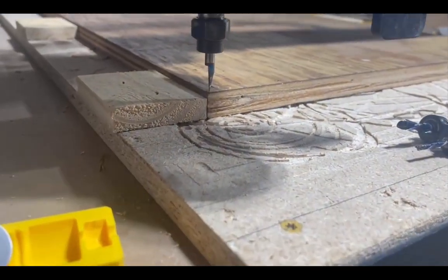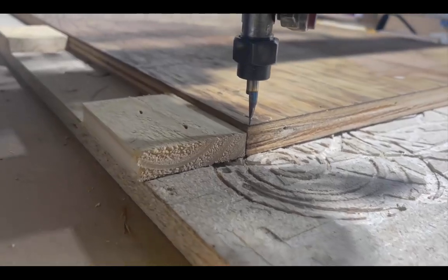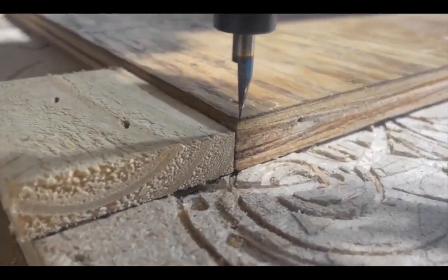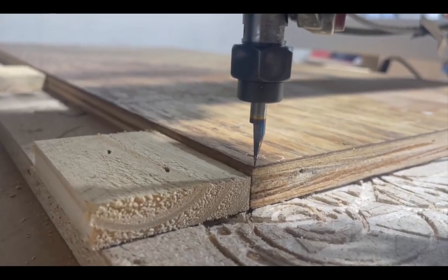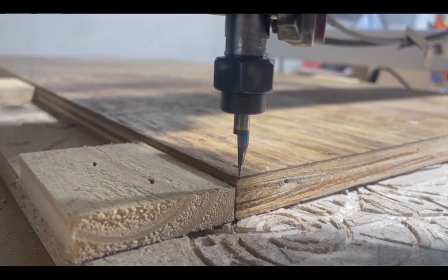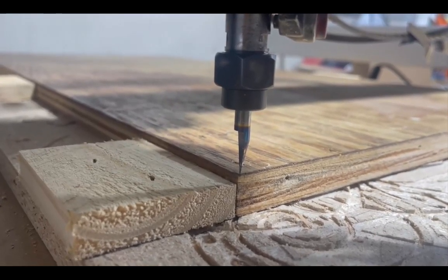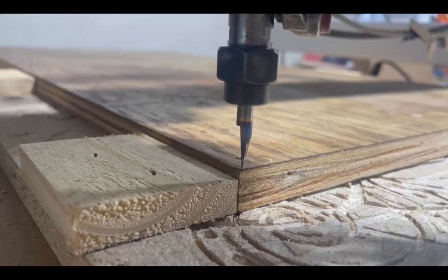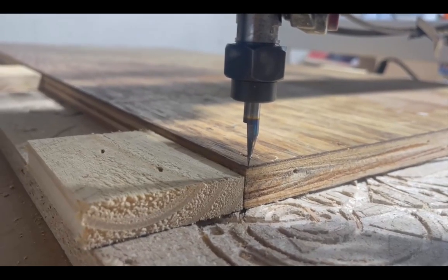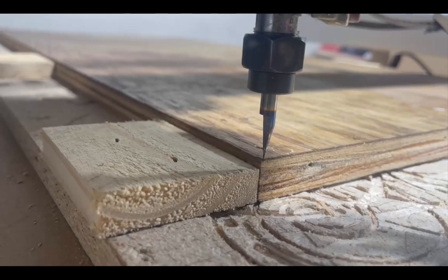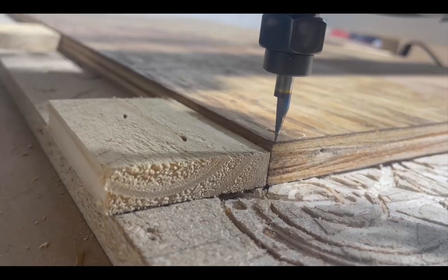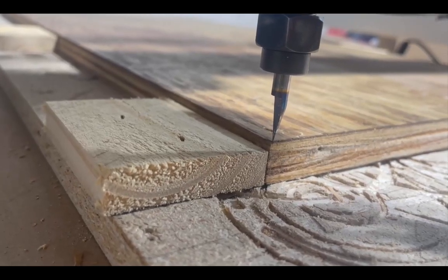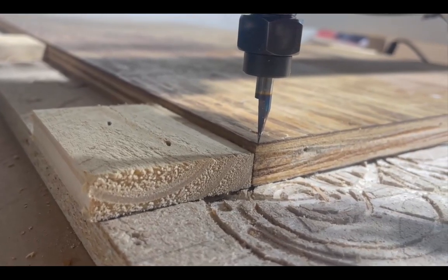Okay, so you can see now that I have moved my XY position right to the corner of my board. Now I can go ahead and set the zero in Carbide Motion and go ahead and start this job. And when I start the job, it's going to raise the Z height here, and it's going to tell me I need to insert my 1/8" end mill. So I will go ahead and begin this process.